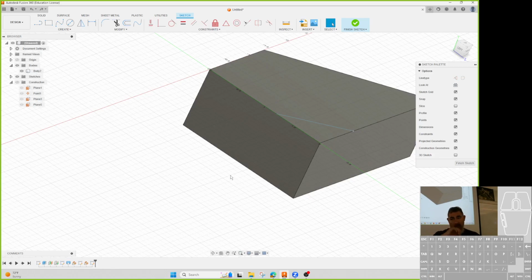So if I can do it with other reference geometry, I'm going to do that. Because even if I have to do several things, it might still be quicker than making that sketch. But this is something that you kind of have to experiment with for yourself. I don't really care which way. Sometimes making it based on a sketch is easier because you can do multiple things at once. Okay. But sometimes you have to use the reference geometry.